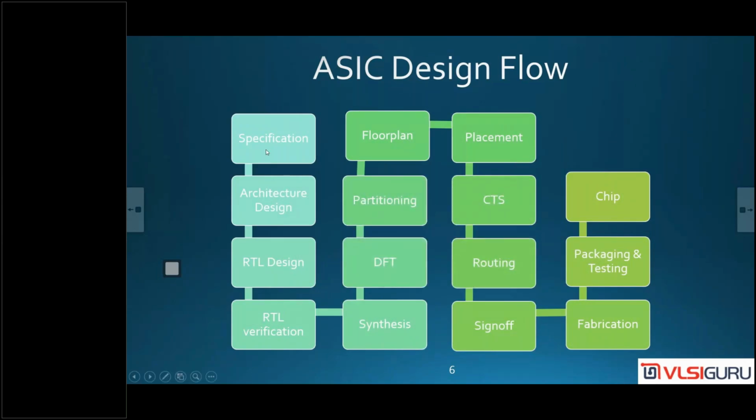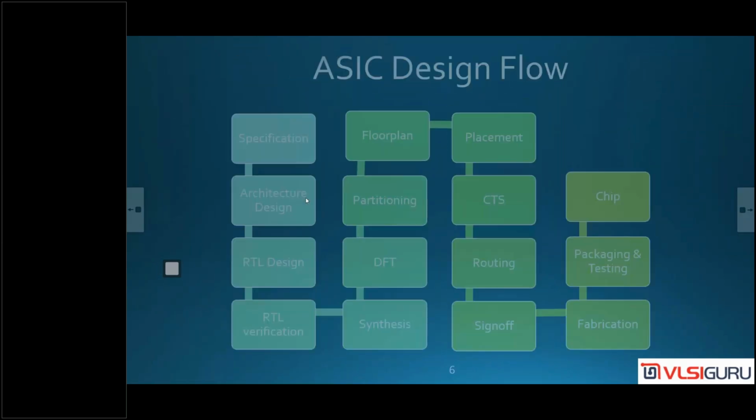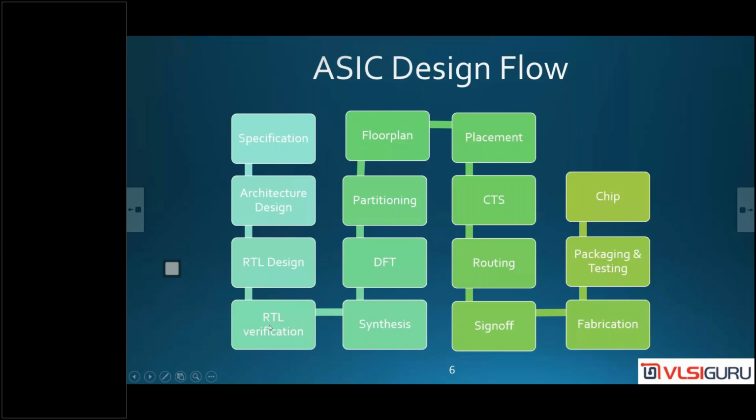We'll start from chip specification, chip architecture, RTL design, RTL verification, floor plan, partitioning, DFT, synthesis, placement, CTS, routing, sign off. Correct. So after that, chip fabrication, packaging, and ultimately the chip will come out.